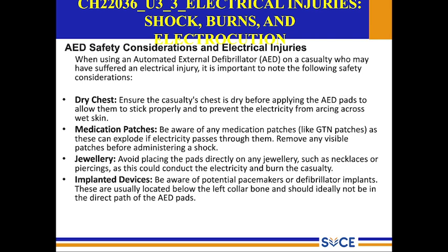AED, that is, automated external defibrillator. AED safety considerations and electrical injuries. When using an AED on a casualty who may have suffered an electrical injury, it is important to note the following considerations. These are the four considerations. First one is dry chest. Ensure the casualty's chest is dry before applying AED pads, to allow them to stick properly and to prevent the electricity from arcing across wet skin.